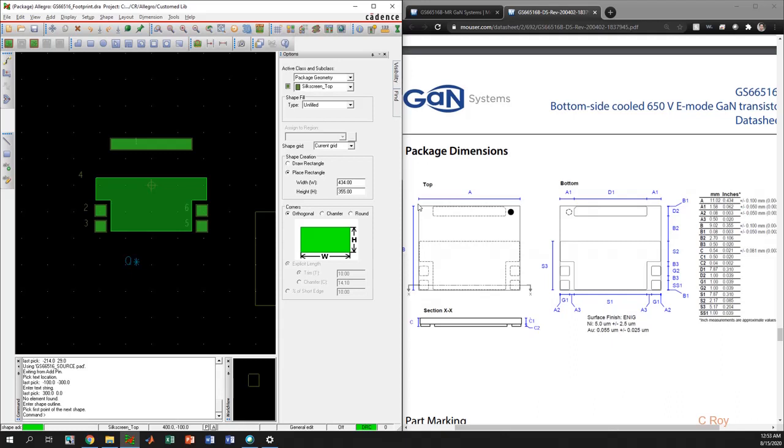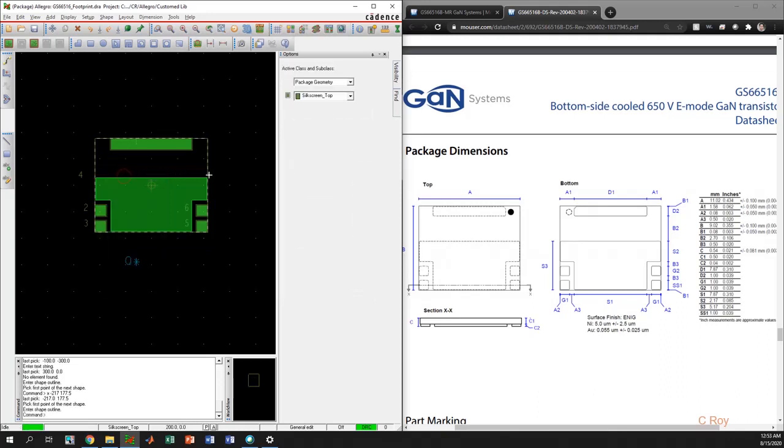To do that, we just have to divide the dimensions by half and use that information. So if we do that, we will get 217 in the x coordinate, and it is negative 217. The y coordinate will be 355 divided by 2, which is 177.5. Okay, so it's placed in the right place. Now it's done, and we have to save this file.